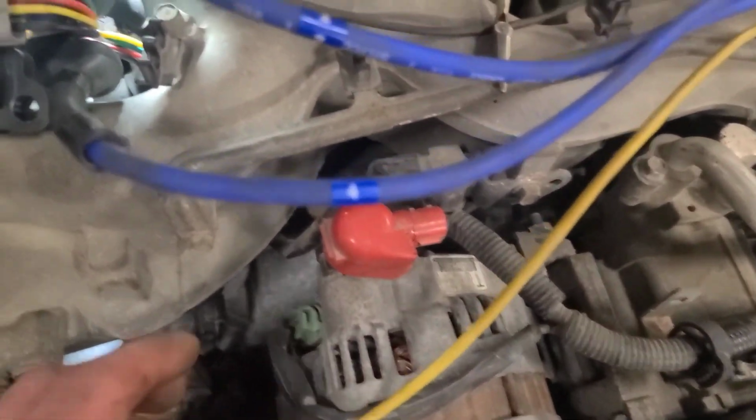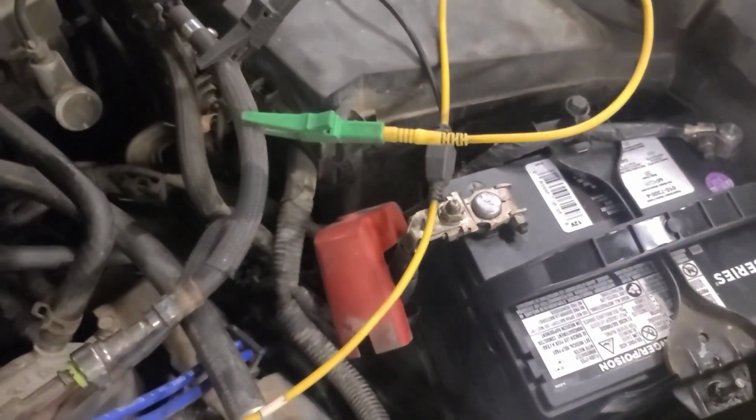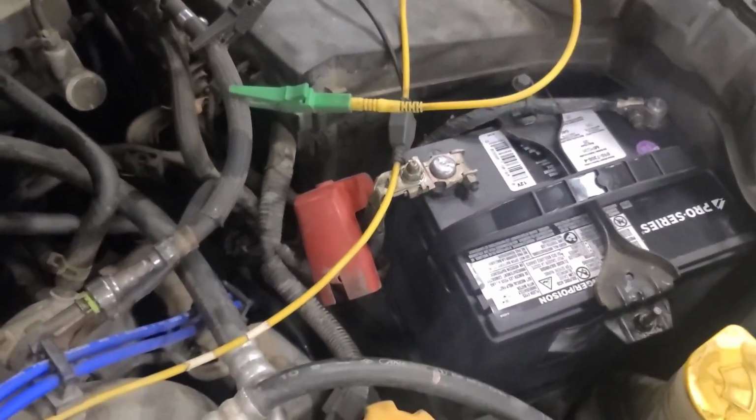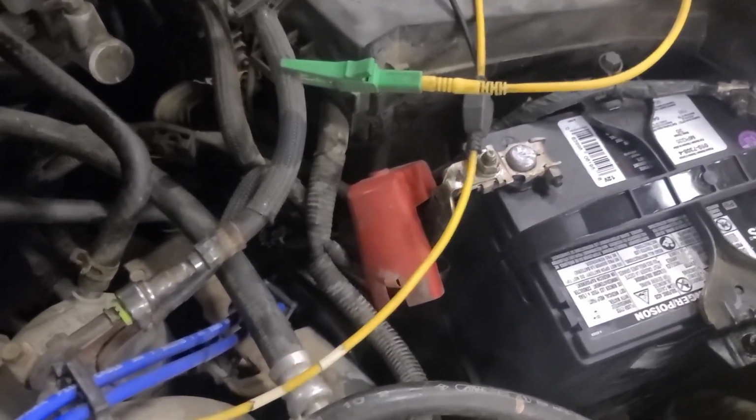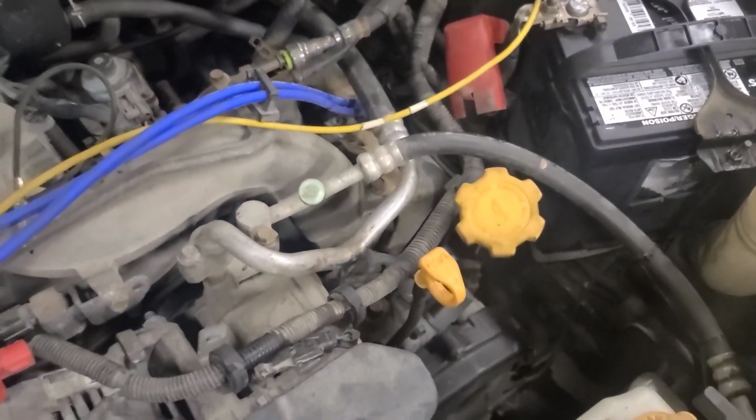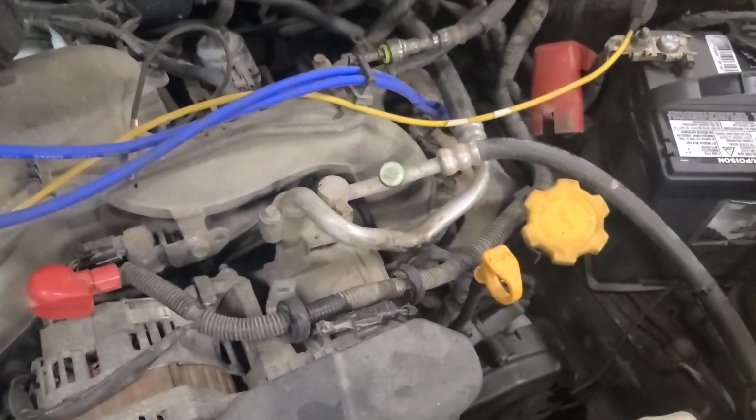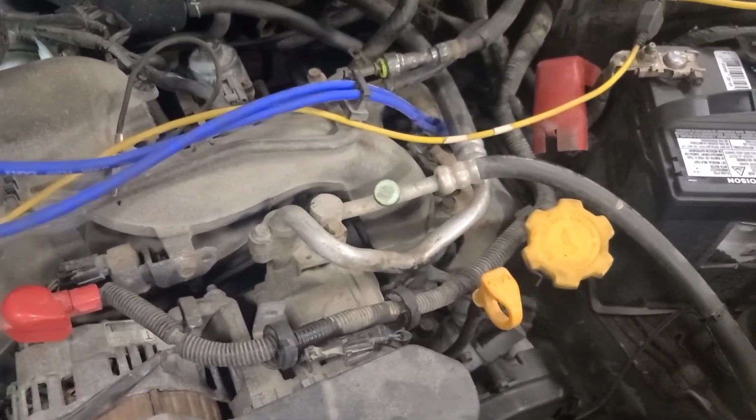I've also connected 4 jumper wires, the universal jumper harness in here. The red wire is power, the yellow wire is ground, and I've connected an alternate power source and ground that I can connect directly to the battery in case there's a voltage drop that I'm missing on the power side. And I'm going to start it and make sure it runs and park it outside and try it again tomorrow morning, take 14.